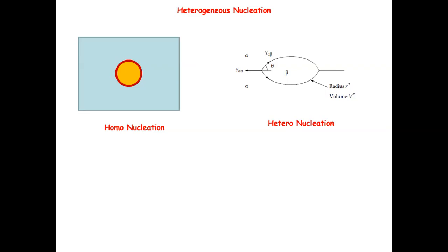The reason is that the grain boundaries, particularly in these alpha grains, are the places where you have a higher concentration of defects. You have a lot of extra room in there. You have vacancies, you have stacking faults at the grain boundaries, and also dislocations and other defects, but the grain boundary is the place where the packing structure is most disordered.